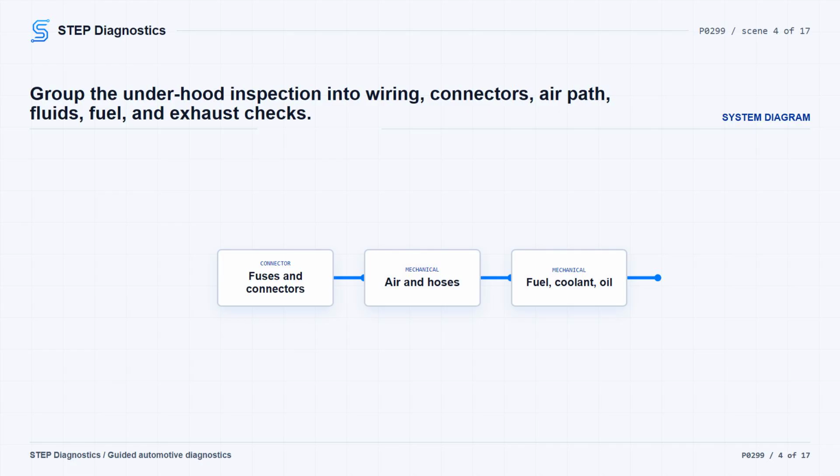Look over the harnesses for damage, chafing, and routing problems. Check fuses, circuits, and connectors for continuity and correct installation. On the mechanical side, make sure components are connected correctly. Then inspect the vacuum lines, air intake system, and hoses for leaks, damage, blockage, routing errors, or restrictions.